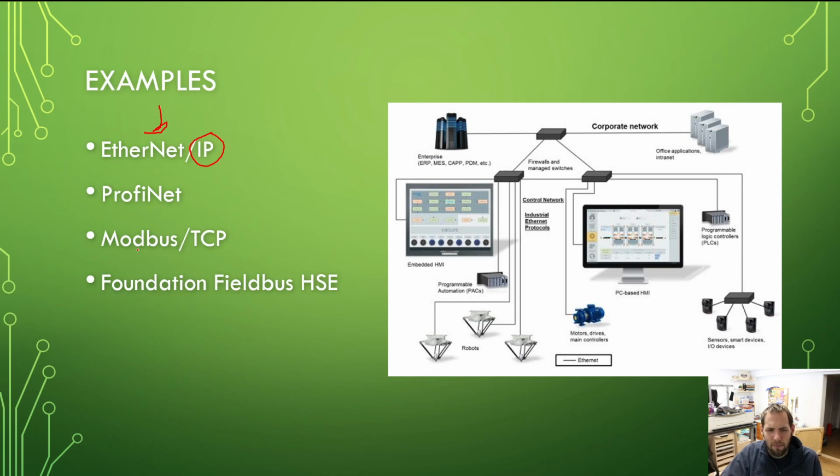That's the CIP layer, which I said is the Common Industrial Protocol. This is Ethernet packets used with the Industrial Protocol of CIP, TCP/IP, and/or UDP layers to provide the required data to your controller. And this does promote consistent implementation of automation functions across diverse ecosystems of products. So again, this is another one of those that they're trying to make a universal thing for, and not everybody is following suit. So that's kind of annoying in the long run.